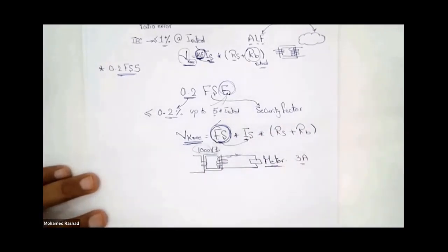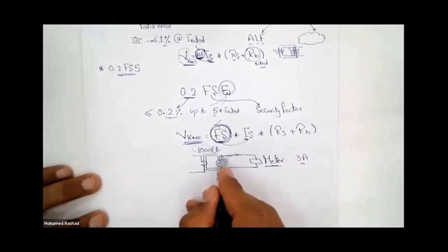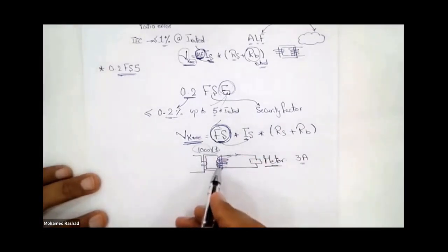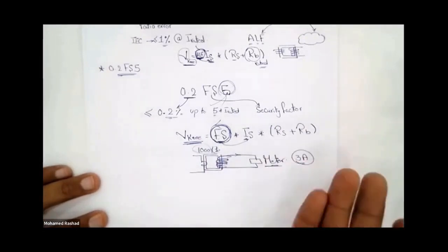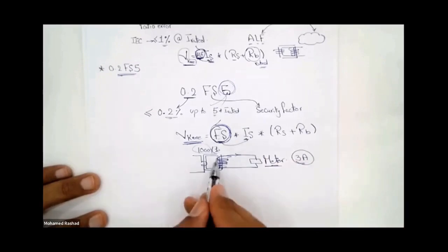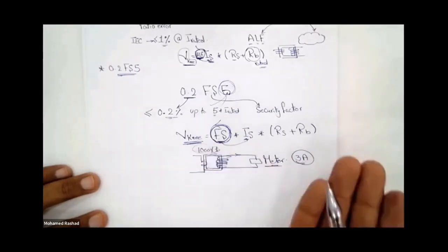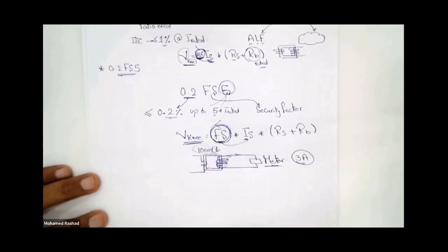Additionally, they call it the security factor for another reason, which is that the cross-sectional area of the cables of your current transformer winding is designed not to handle high currents at all, because it is assumed that the core should quickly reach saturation. And why? Because practically, I am not going to transfer these high currents. The meter is not interested in reading these high currents, therefore I don't need them.